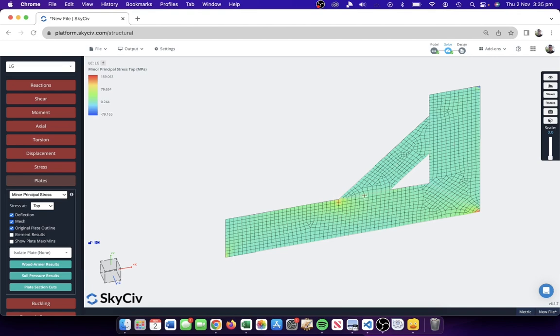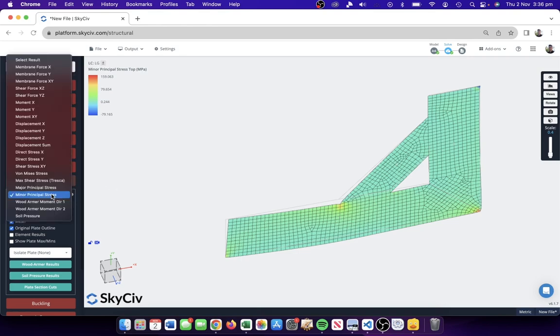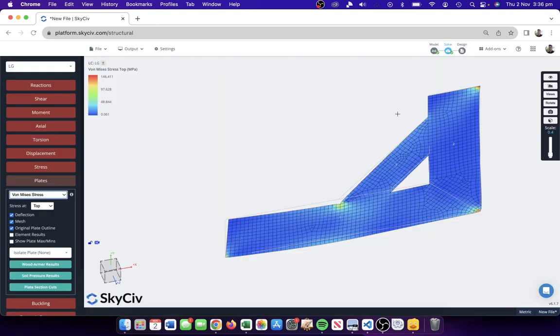And also I want to see the type of stresses that we are receiving. They're quite concentrated. So that is a bit of an indicator that maybe we've applied the load at one concentrated point, or it is an indication of a weak point of the structure. I can see that there are some large negative stresses here, especially if we go to the von Mises. We'll see some peak stresses up here in this corner, where the supports are and where the point load is applied.